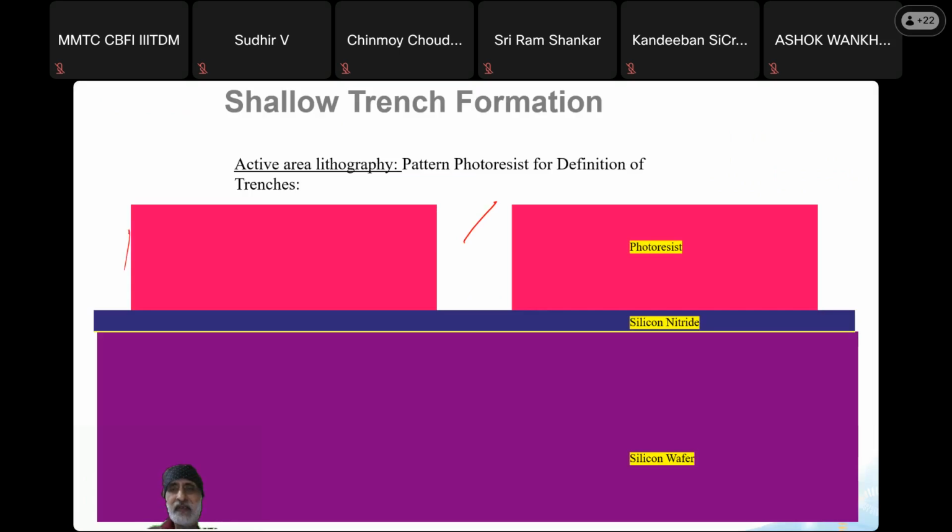And then we will put a photoresist, and there will be a mask, then the light will shine, and then depending on the positive photoresist or negative photoresist, the photoresist will be weakened, this window will open, and once this window is open, I will do the etching to remove this layer, which is blue color. Then I will use another window to etch out this yellow color also. So both these will go, but where red is there, nothing will happen.